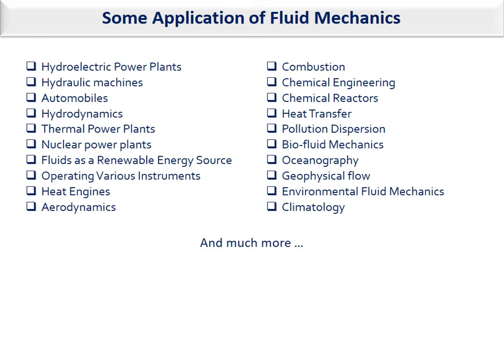in order to calculate the temperature distribution in a fluid, you need the velocity components to be calculated first, or if the flow is coupled like natural convection, then you should solve all the equations together, the equations for the flow and the equations for the energy. So it is a really important topic.